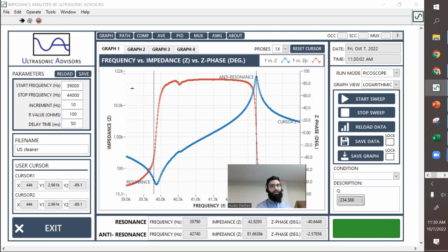So let's get into that question of conductance, which can also be called real admittance. Any impedance analyzer or network analyzer can also plot something called conductance, which you can say is the real part of the admittance. You can go online and look up what different representations exist for impedance. Instead of impedance, you can do the reciprocal of impedance, which is admittance. So it's showing how much current is flowing versus how much current is being resisted.